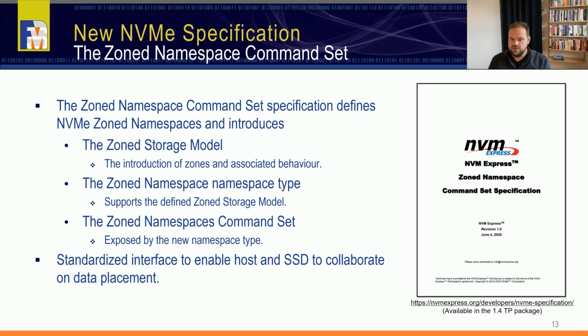It was released back in June, and it introduces the zoned storage model, the introduction of zones and their associated behavior, the Zoned Namespace type inside of NVMe which supports this model, and the Zoned Namespace Command Set, where this namespace exposes new commands, like Zone Management Receive and Zone Management Send, while you can still do read and write and so on.